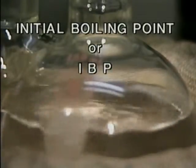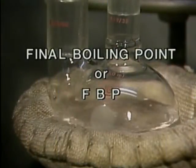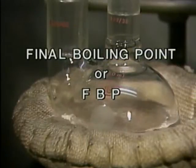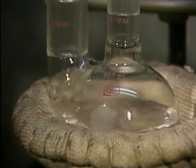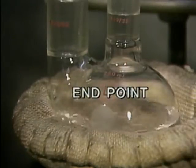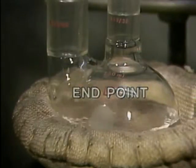The boiling point of the component in the mixture that boils at the lowest temperature is the mixture's initial boiling point, or IBP. The mixture's final boiling point, or FBP, is the temperature at which the component that has the highest boiling point boils. The final boiling point is also commonly referred to as the end point of the mixture. The end point is the end of the mixture's boiling range.